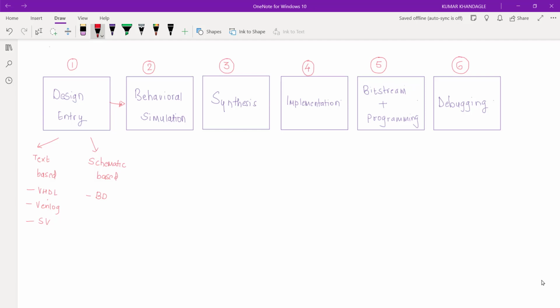Let us assume we haven't performed synthesis as well as implementation. That represents the first simulation, where we just apply a stimulus and observe the response that we are getting on an HDL code. That is pre-synthesis behavioral simulation. The next one is post-synthesis behavioral simulation. After we perform a synthesis, we again perform a behavioral simulation because there will be differences.